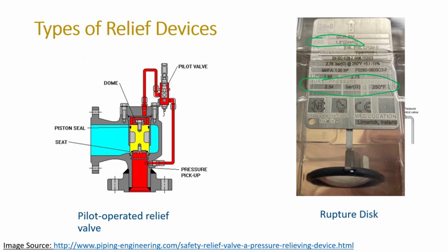Some downsides to rupture discs is once they burst, they remain open. And that could result in the total discharge of your process materials, or you could then have an avenue for air to enter your system, and this could result in a flammable atmosphere if you have a fuel inside your vessel. Also, these rupture discs could burst and be unnoticed by operators.